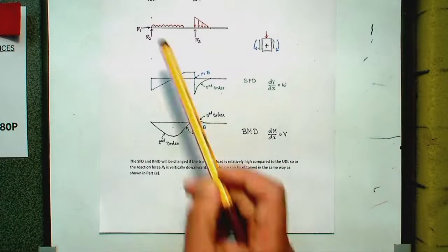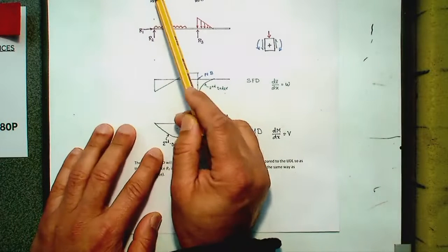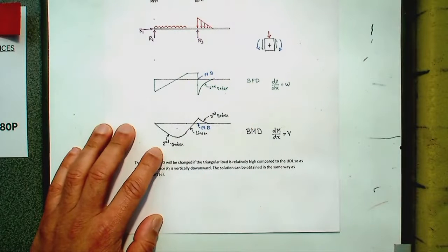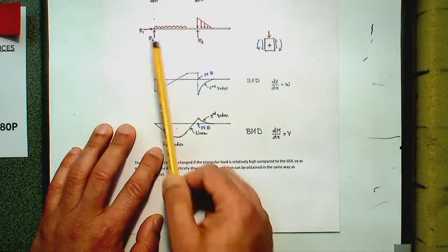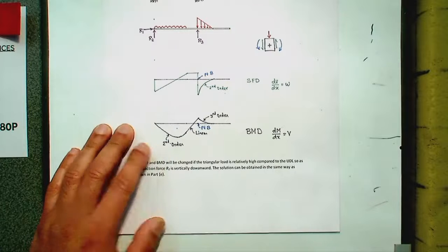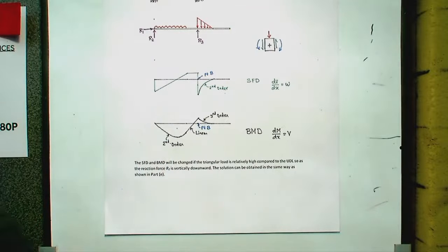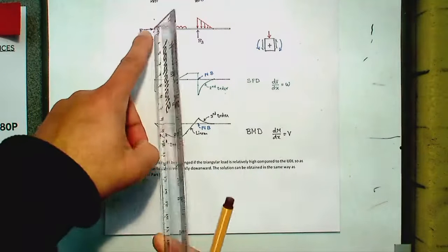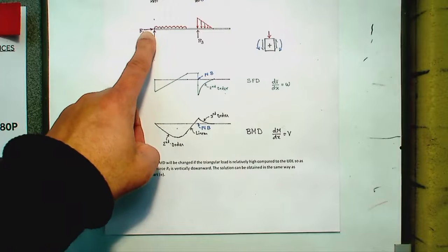So G has got this force system. You have got a UDL and a triangularly varying load. So the reaction force free body diagram wise would be like this. What about the shear force diagram? So again, we go dV/dx is w. So this R2 is upward.